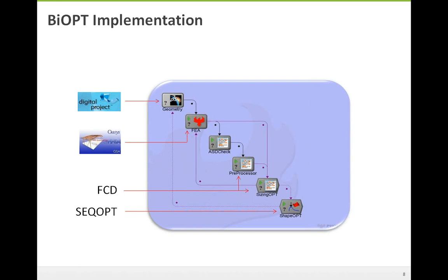There are techniques to wrap the input and output files, so you can change the values in those files or extract values, and then automate the execution of the tool. If you can automate the tool in one of those two ways, that's really the only requirement. Of course, it has to be able to accomplish the function you want, but designers and engineers already know the capabilities of these tools, so that's usually the reason for selecting a tool in the first place.